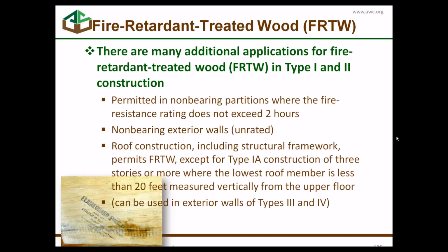These permissions are in addition to their appropriate place as part of the exterior wall in type 3 or type 4 construction. In addition, you have a rather large exception for use in roofs and nonbearing exterior walls and so forth.